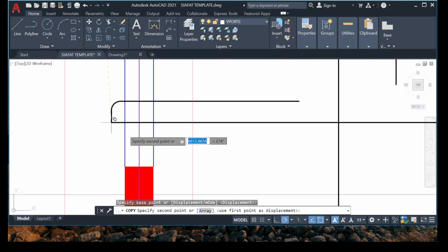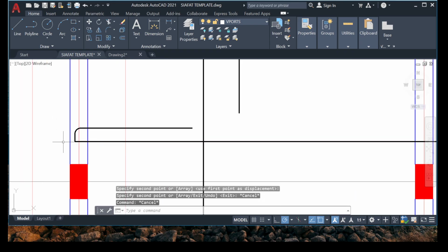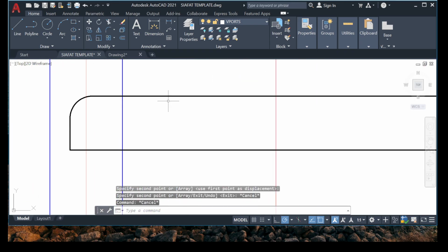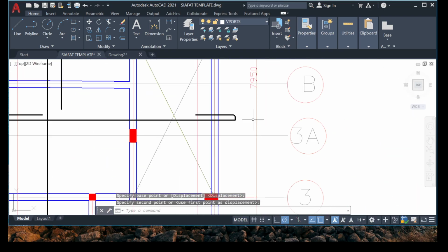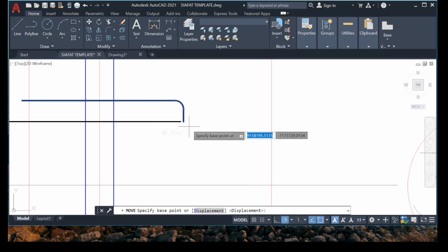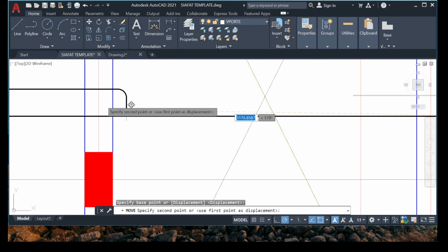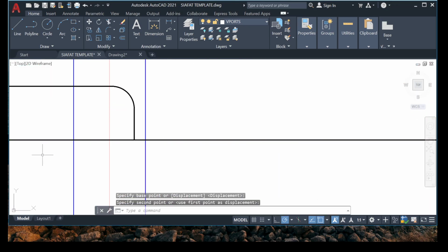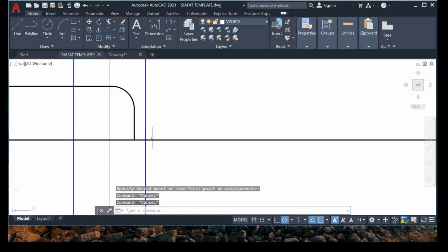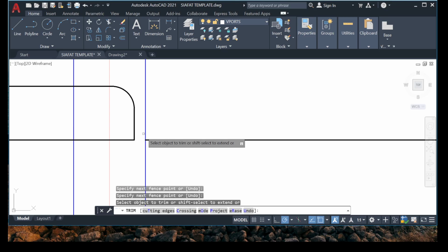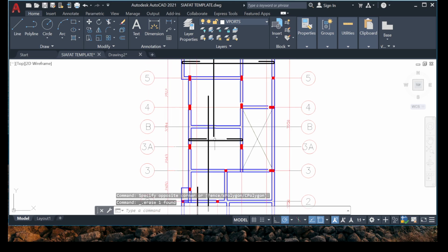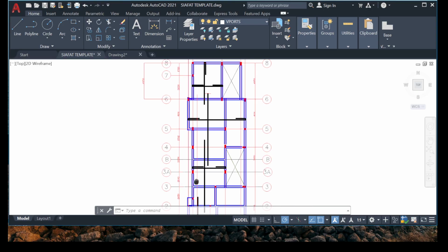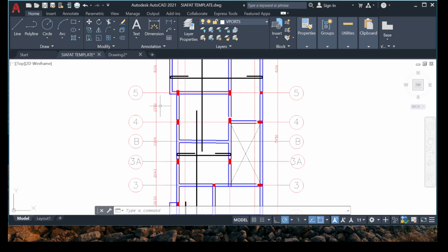Yeah, so let's bring in this for this. Ensure that your concrete cover is 125 mm. Very good. So this one is going to stop here. So now all I need to do is just move this, and bring this here. So slab detailing takes a whole lot of time. So that's why you need to be very, very careful because once you make a mistake like this, then they will go and make the mistake on site. So this is what we have here for this particular panel.